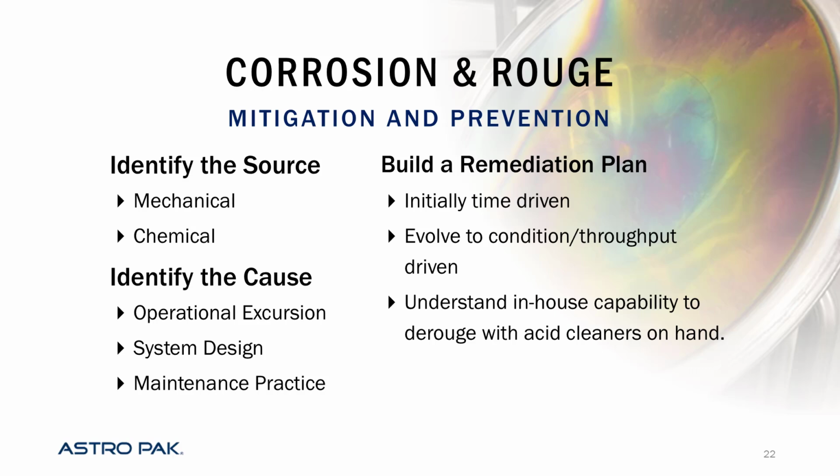The cause: was it caused by an operational excursion? Did temperature go above your alarm for a couple hours and that was enough to accelerate a reaction more than what your maintenance is comfortable with or used to? The system design: was an incorrect alloy used when you replaced a component? We had an issue with galvanized being used instead of stainless at one point about 1.5 years ago. They look pretty similar, but not fully similar. Or gasket selection: was the wrong gasket used when replacing your seals?